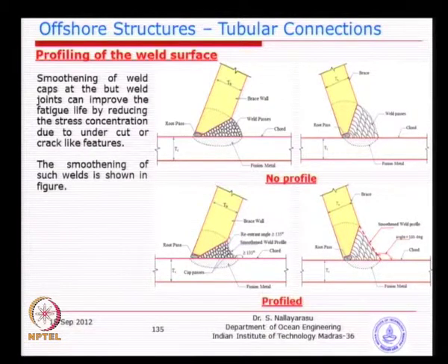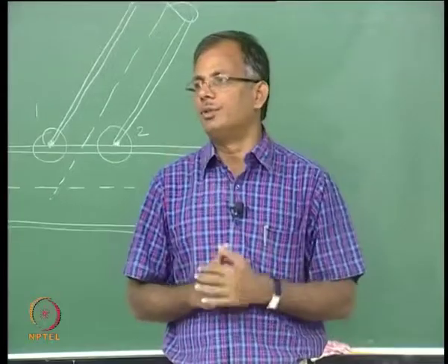Now, if you look at this, when you go into this particular junction, the connection between the brace and the weld, you will see that the surface is not that smooth, and because of that you will see an increased value of stress concentration at that location. Along the weld you will see several changing surfaces. And finally, when it comes to connecting to the chord at that location, it is also a notch, basically a change in angle, and it is not smooth enough.